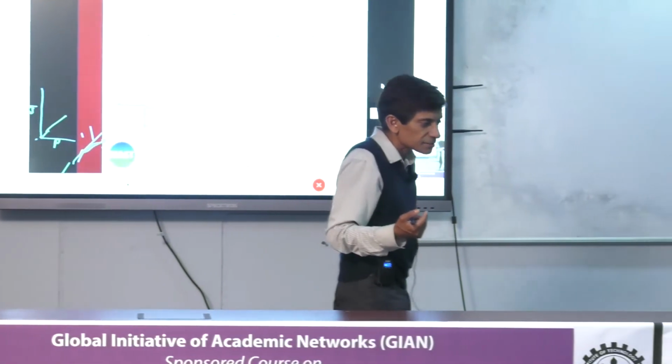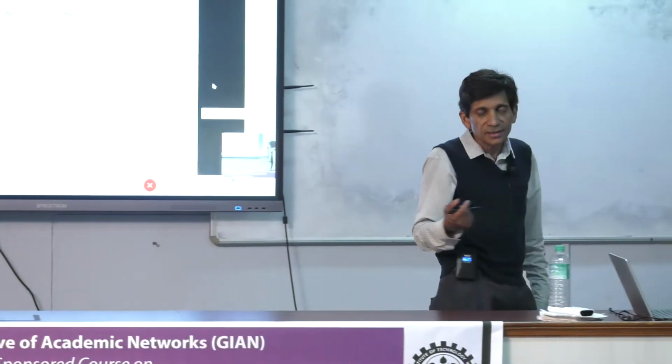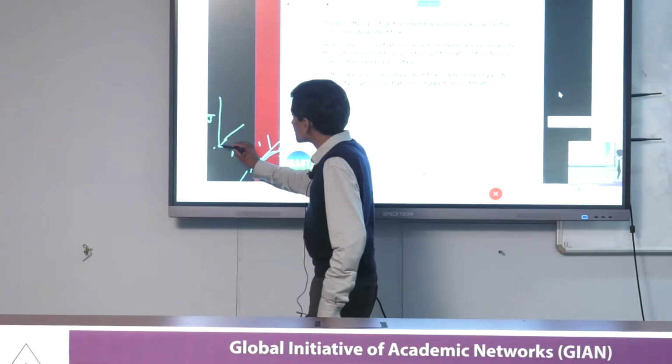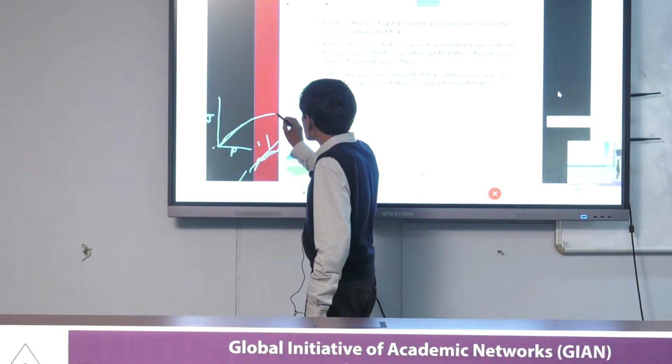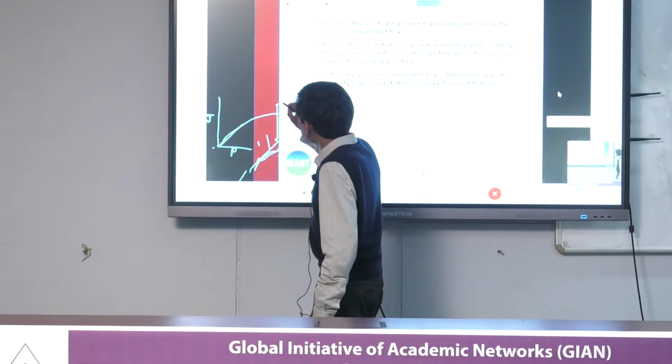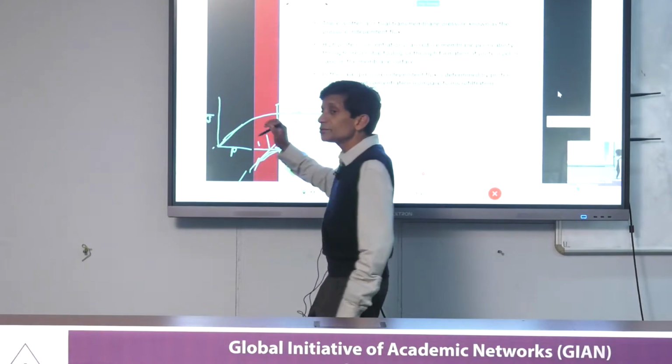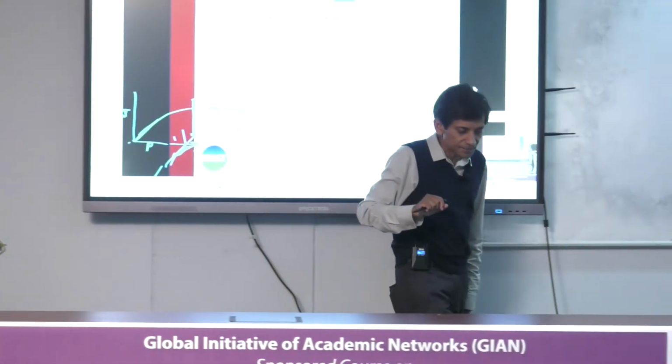So further increases in pressure will not lead to an increase in flux. Actually, these curves typically do something like this. There is a linear region, and then it typically curves off like that. But operating in this region is quite dangerous, because you can have big increases in pressure that only lead to very minor increases in flux.